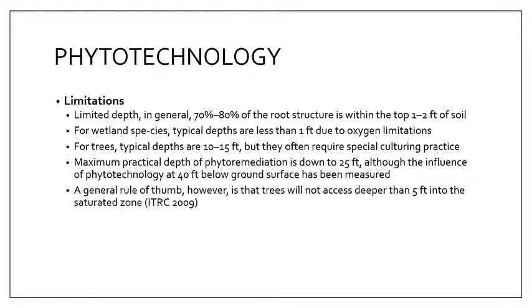So you can practically just remediate the upper 1.5 meters of your groundwater when you're using phytotechnology. It's mostly about the penetration depth. That's the main limit of your phytotechnology.